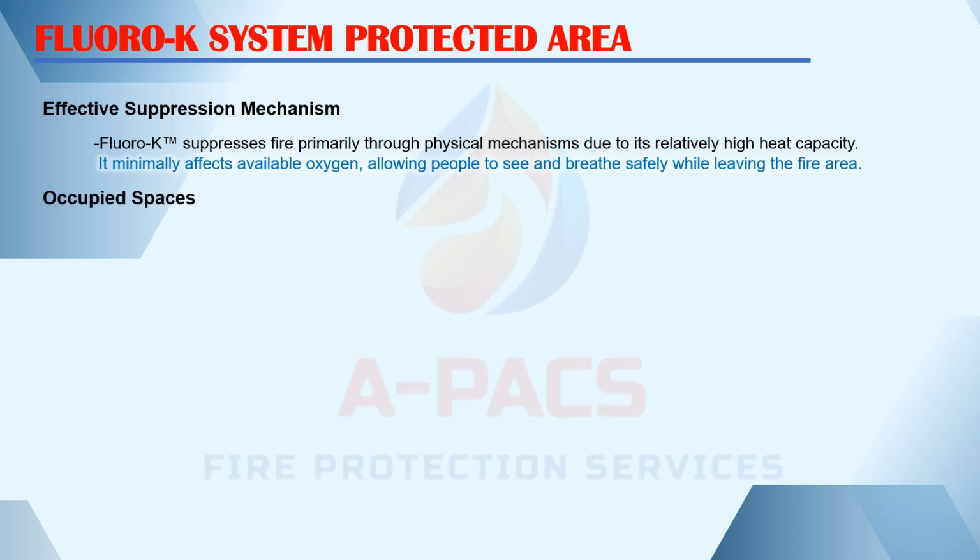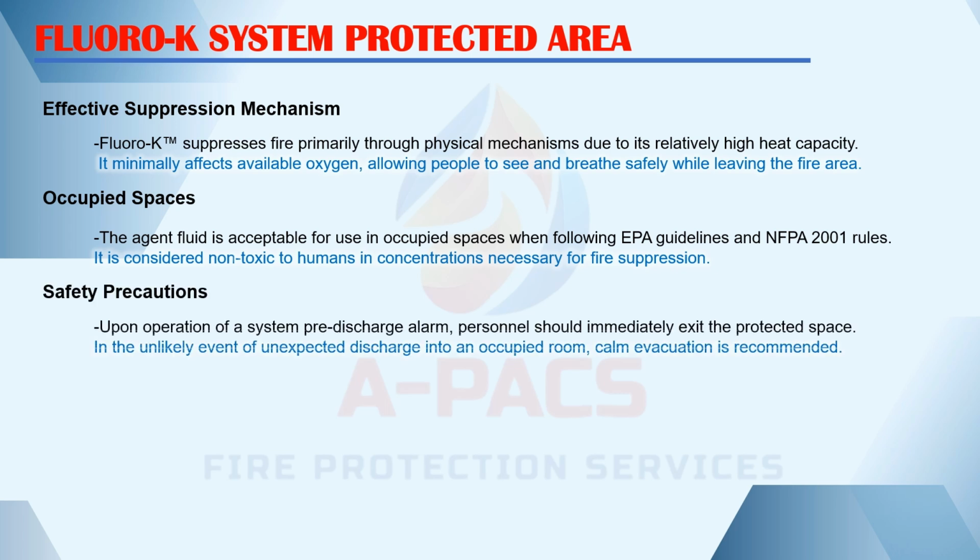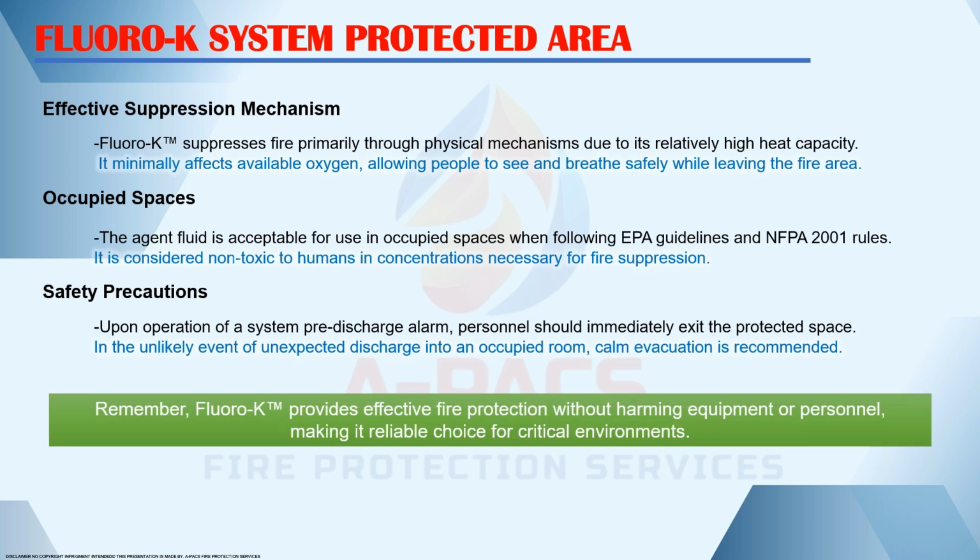The occupied spaces. The agent fluid is acceptable for use in occupied spaces when following EPA guidelines and NFPA 2001 rules. It is considered non-toxic to humans in concentrations necessary for fire suppression. And the safety precautions. Upon operation of a system pre-discharge alarm, personnel should immediately exit the protected space. In the unlikely event of unexpected discharge into an occupied room, calm evacuation is recommended. Always remember, Fluoro-K provides effective fire protection without harming equipment or personnel, making it a reliable choice for critical environments.